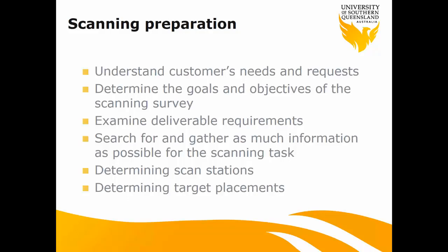For example, if your final product needs the laser scanning data in a specific coordinate system, you probably need to search for some permanent control marks or existing control marks and the related coordinates for georeference.